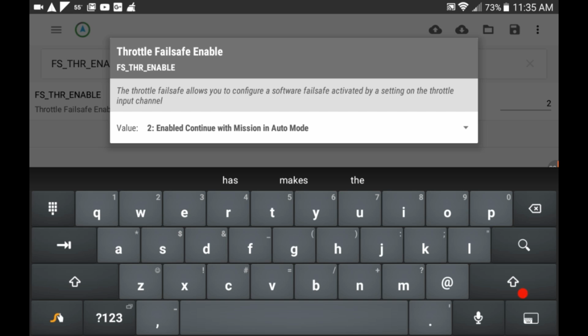So wherever you took off from, you want to make sure that Solo is going to be at least visible in the sky for you to have controller signal to issue a return to land from your controller, or to bring it down manually using the flight stick. Okay, so if you're going to use this parameter, you have to make sure that the last waypoint isn't somewhere off in the distance, that it's somewhere close to you, where you're going to actually have line of sight to Solo. Okay, so you have to be careful about that.